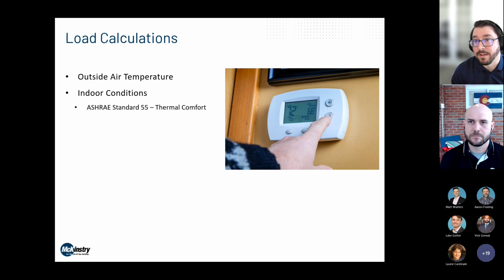And on the flip side, speaking to climate change, extremes get pushed both ways. We've all probably experienced a bit of the more extreme highs and more extreme lows that have been happening more in recent years. So you will find, especially for critical applications on the low side, say a 100% central air system, like a makeup air system at an operating room or something like that, they might design to a little bit lower than that 99.6 heating temperature because it's a different way of applying a safety factor.